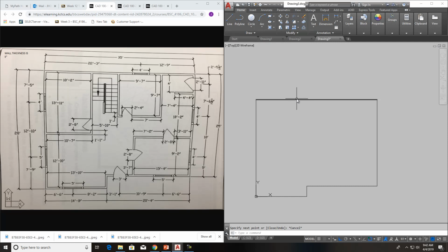Now this whole thing here is a 5-inch offset. I could make this a polyline and offset it all at one time, or offset it individually. I want to make it a polyline, so I just type in PE, enter, click on one of them. You want to turn it into one, Y for yes, then join, and I'll join all of it together, and now it's a polyline. Use my offset tool, 5 inches, grab it, and offset all of it in just like that.